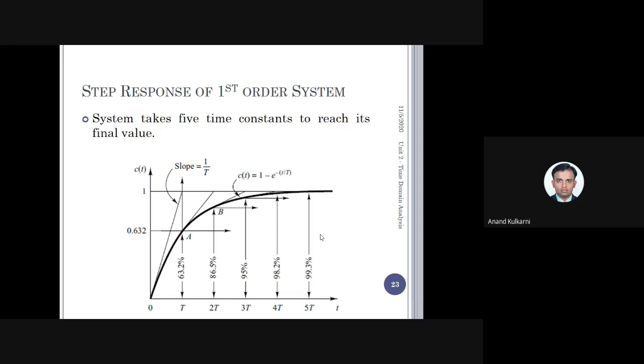degree Fahrenheit. That is approximately your body temperature, for which I have taken an example of 100 degree Fahrenheit. So that means the doctor has to wait a minimum of 5 times the time constant. If the time constant of the thermometer is 10 seconds, he has to wait for at least 50 seconds before he takes the reading. And the longer his wait, the better the reading will be.